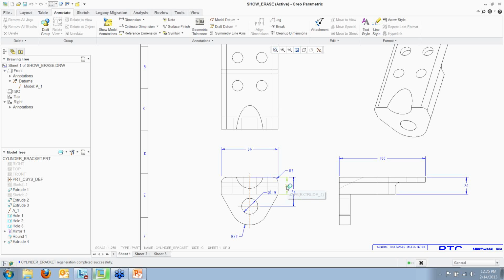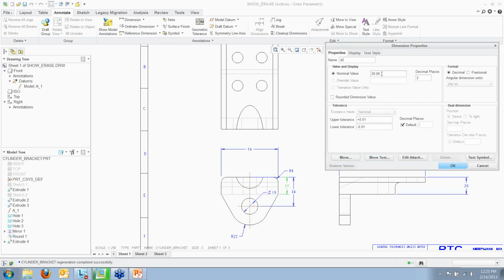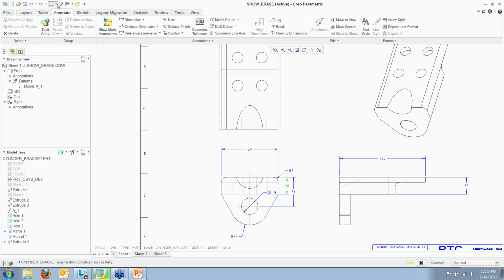So that allows me to change something right here on the drawing without having to go into another window or into another model. Now that being said, this is very powerful. It is also very dangerous. If you have users that say, oh, I need to make one drawing that looks exactly like this, but I need this to be 30, and he comes in and changes this to 30, then guess what? When I regenerate this, everywhere where this part is used, not only every drawing of this part, but every assembly that this part is in changes.